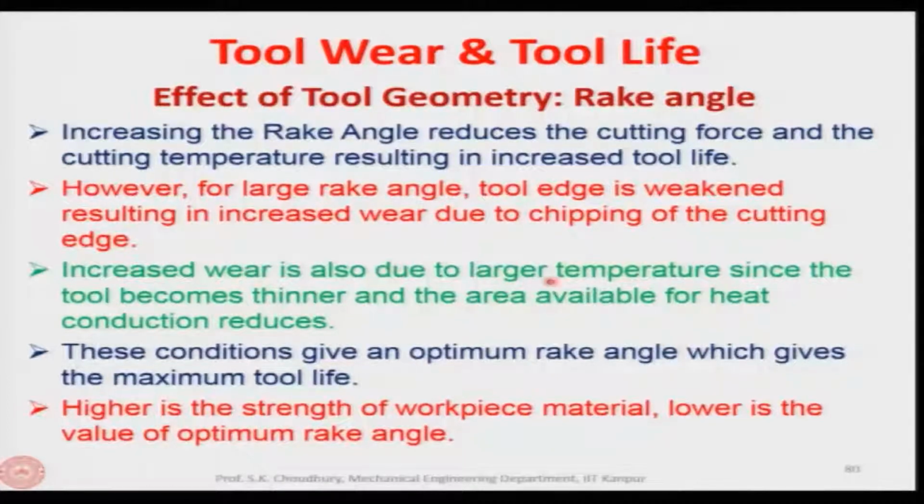Increased wear is also due to larger temperature, since the tool becomes thinner and the material available for heat conduction will be less. This also we have discussed earlier. These conditions give an optimum rake angle which gives the maximum tool life, as I said. The higher the strength of the workpiece material, the lower the value of the optimum rake angle. It is obvious: if the strength of the workpiece material is higher, the force required will be more, and then it will reduce the tool life.